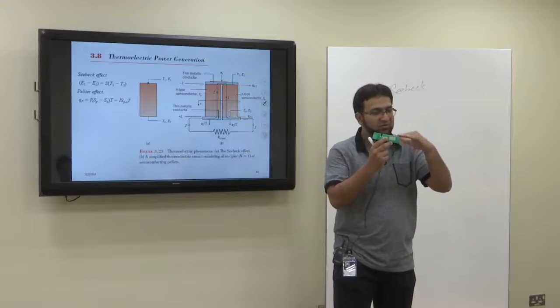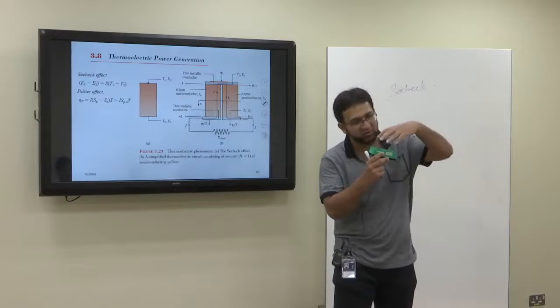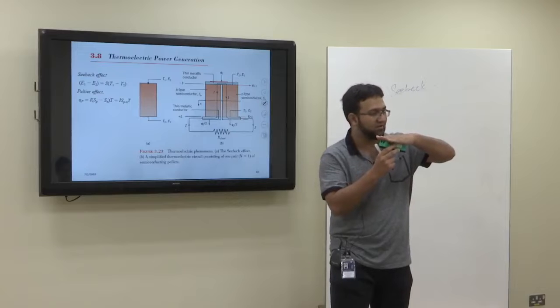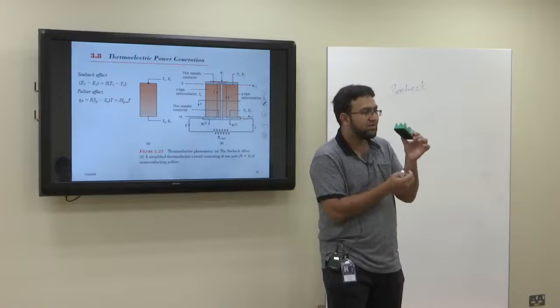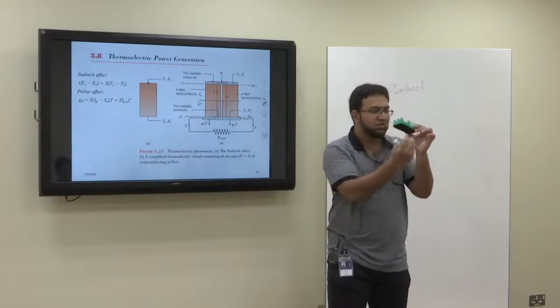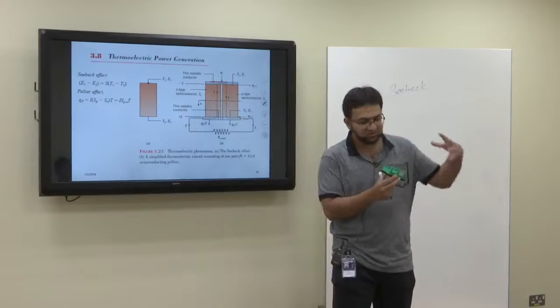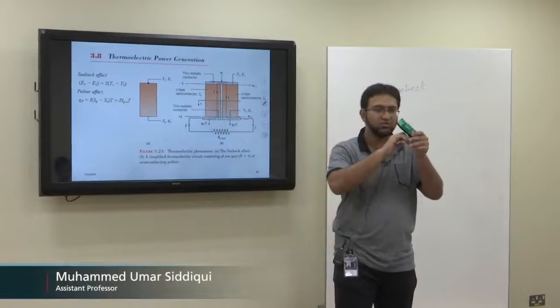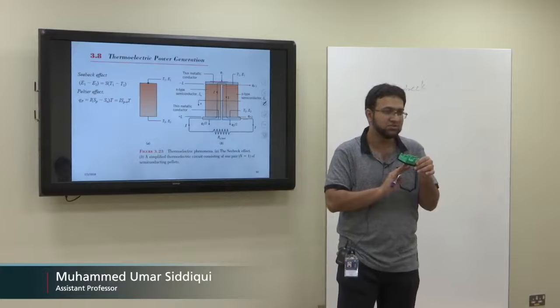So when the temperature of it drops from 500 to a little down, you supply more energy so that it keeps at 500. And you keep on rejecting heat from the bottom. So when the temperature rises at the bottom from 50 to, let's say, 60, you reject heat and make it 50 again. So you need a continuous heat supply at the top, you need a continuous heat rejection at the bottom to maintain the temperature difference.